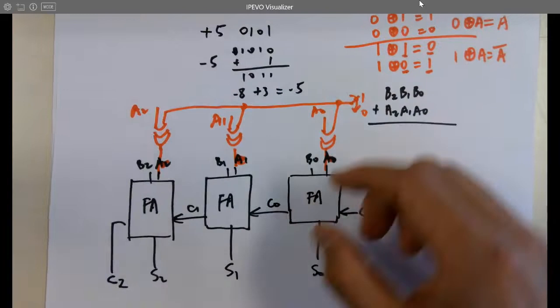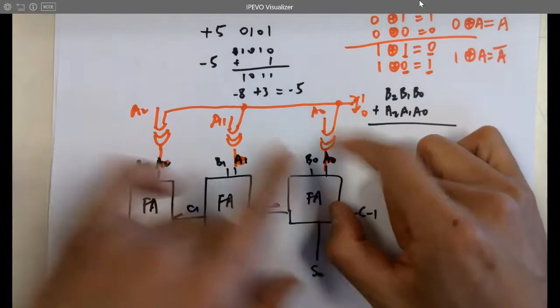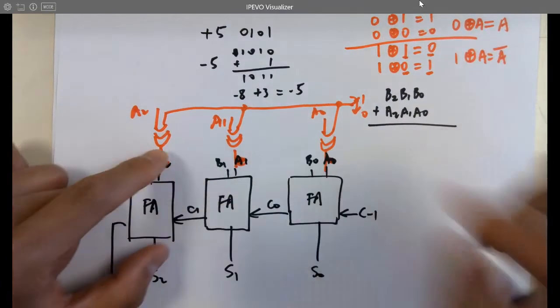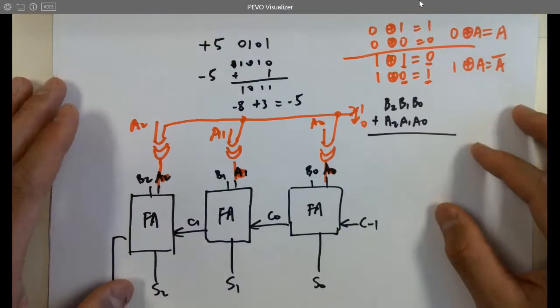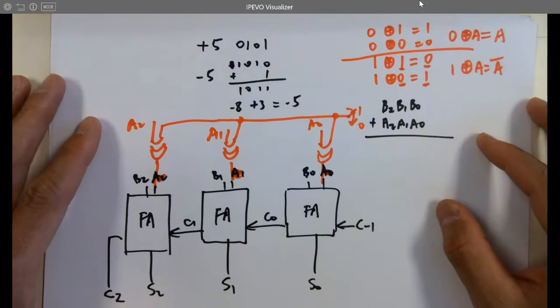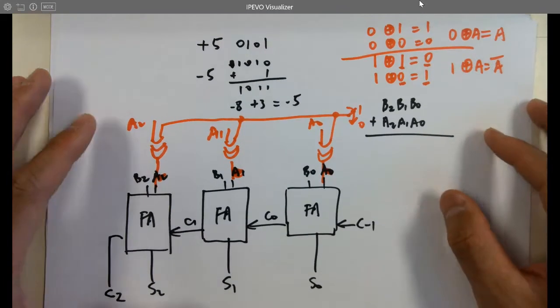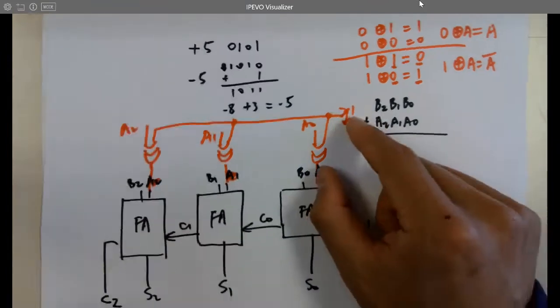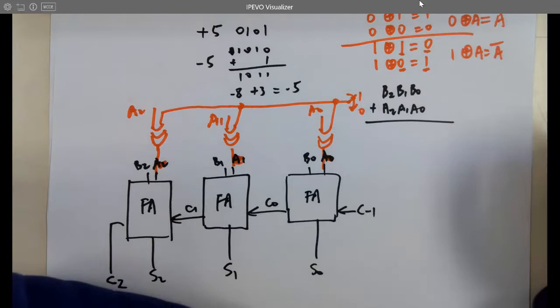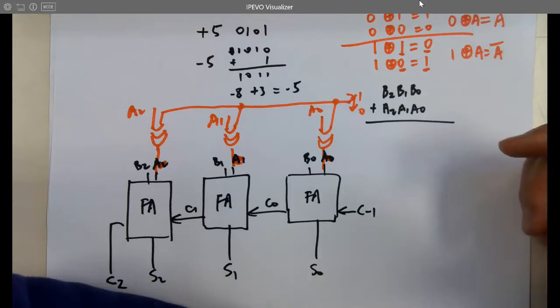So it's either sending A's here or sending A's complement here. What else are we missing for 2's complement? You need to add 1. Where should we add that 1? For example, we want to do a subtraction instead of addition. You want to turn the switch to where? 1. So we get a negative number, right? It's a subtraction.